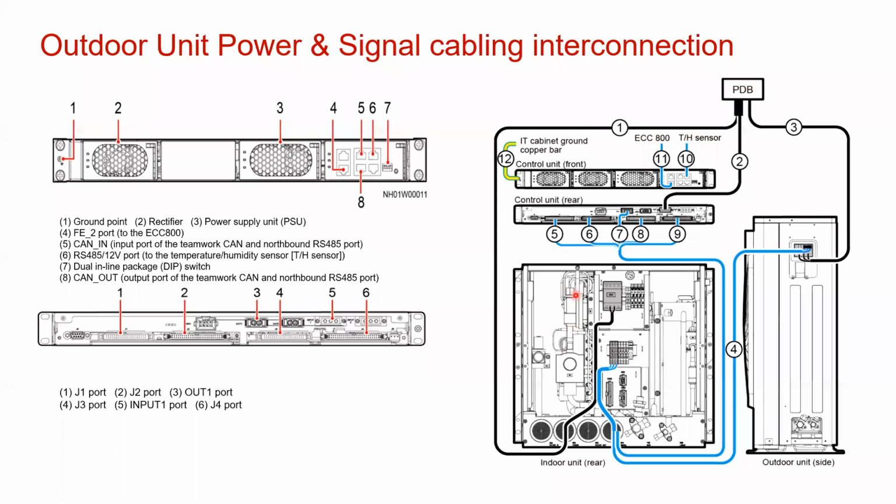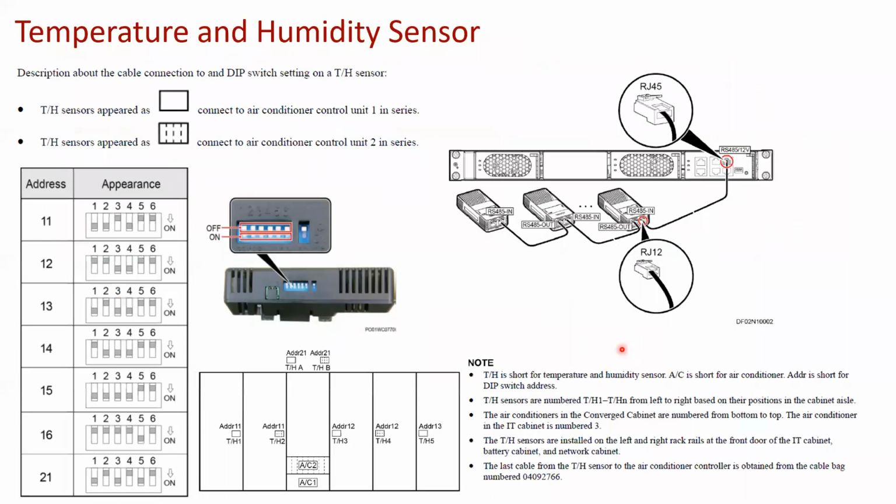So it is automated, and we can do the teaming also. Like I mentioned, 2 AC, 3 AC, we can team them together and choose that one will operate at a time, another will shut down at that time to save the power costing and the operational costing. Okay, so the next part is the temperature and humidity sensors.